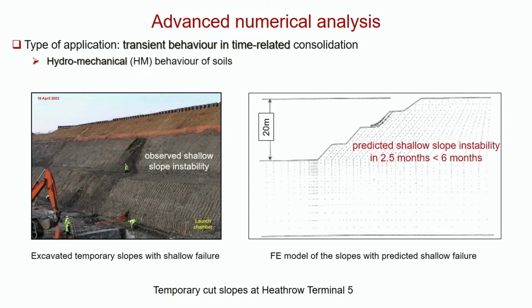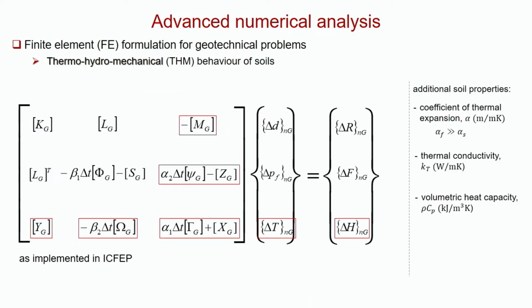London clay is also a strain softening material, so we get progressive failure. And we did the analysis, and the analysis said that to get a deep-seated slope, it was going to occur in about 6 years. They only had it open for about a year and a half, so that was fine. But the analysis showed that we were going to get superficial slides, and exactly what they got during the time it was open. So this is neither short-term nor long-term, but adding the complexity to the analysis, and of course to analyse this you must do numerical analysis, allowed us to do so.